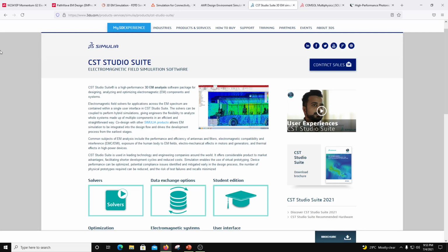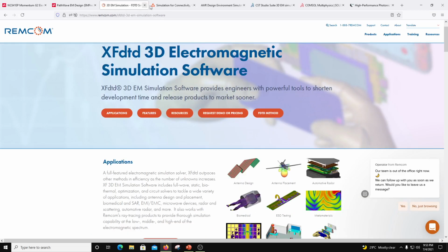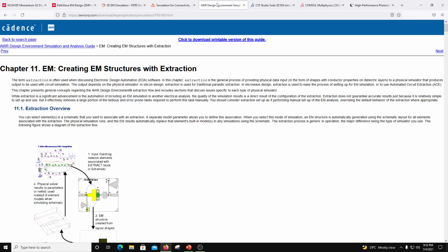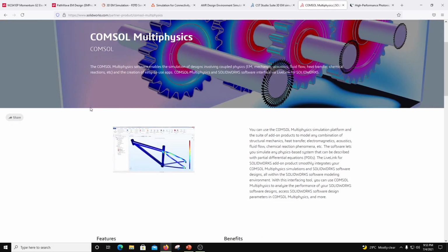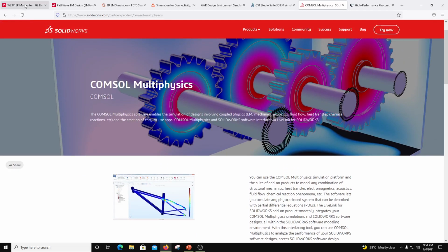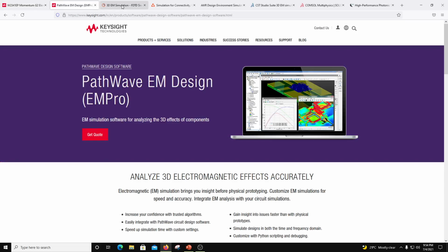Whenever you have a charge which moves under the effect of a field, these simulation softwares cannot be used. In that case you have COMSOL. That is why you cannot do active devices in these simulation tools, because they are Laplacian solvers. They don't deal with carriers or carrier distributions, because they are based on the assumption that there are no charges which move under the influence of fields.